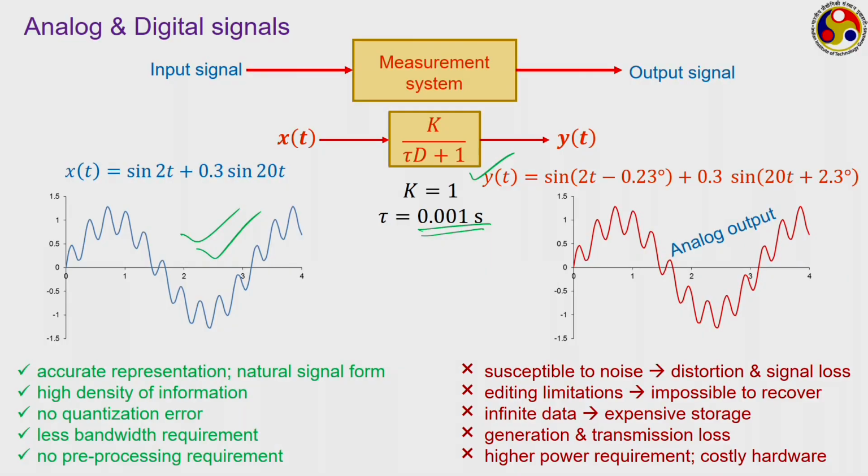Also, if there is a vibration of the floor where you are doing the experiment, that may get reflected. Another big issue may be there. Suppose this is your mercury column, this is the U, and this is a U-tube manometer, and this is your mercury column, this is the height difference that we are talking about.